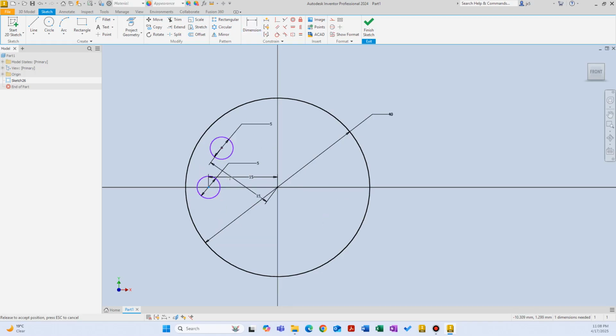Yeah, so right now it is also moving to that direction. So maybe let's just assign a line here and call that a construction geometry. That way it is fully defined. And instead of measuring that, let's just measure this. Okay, so you didn't have to fully define this. I'm just trying to make sure that everything is fully constrained and it doesn't move around as we practice.